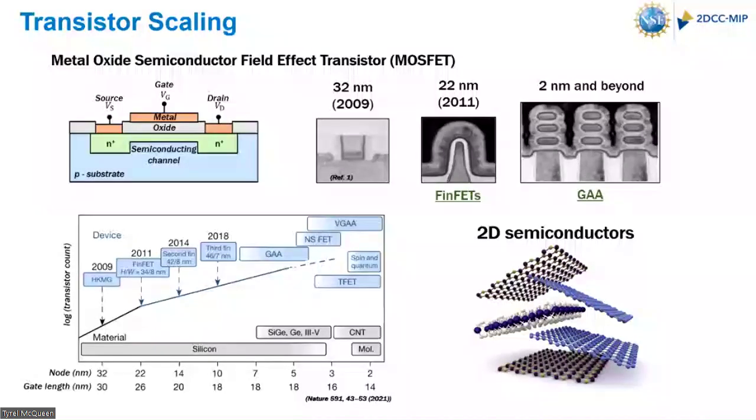Oh, sure, yeah. Show that the gate doesn't actually change. Yeah. So why do we call these the 2 nanometer node and stuff? Yeah. So right. So you're not physically scaling the gate width or the channel length, but you're still packing more transistors into a given area.